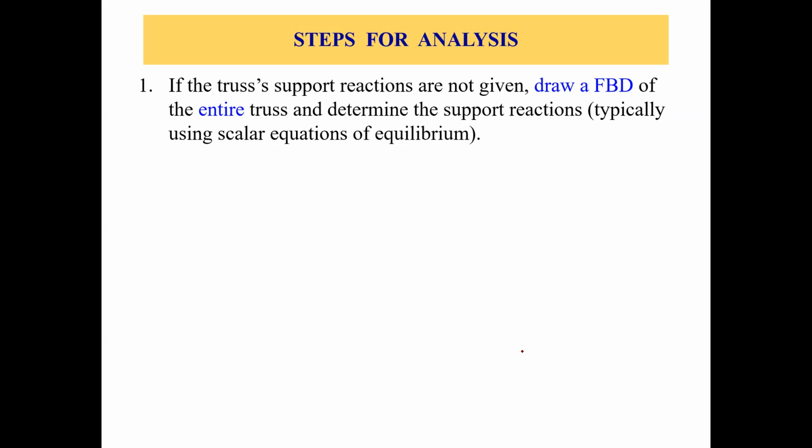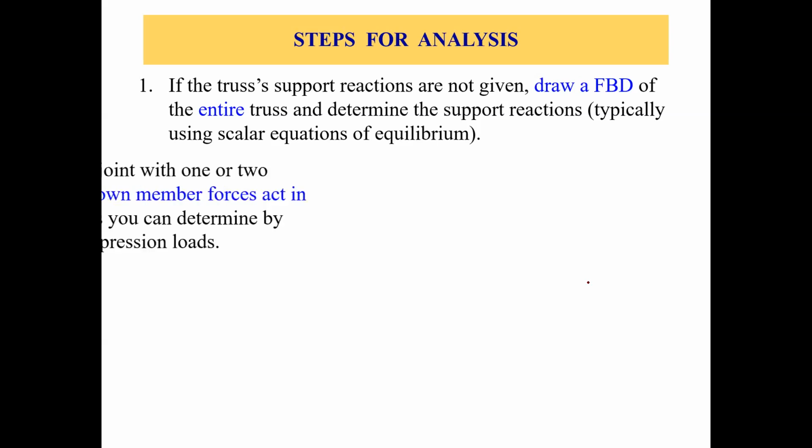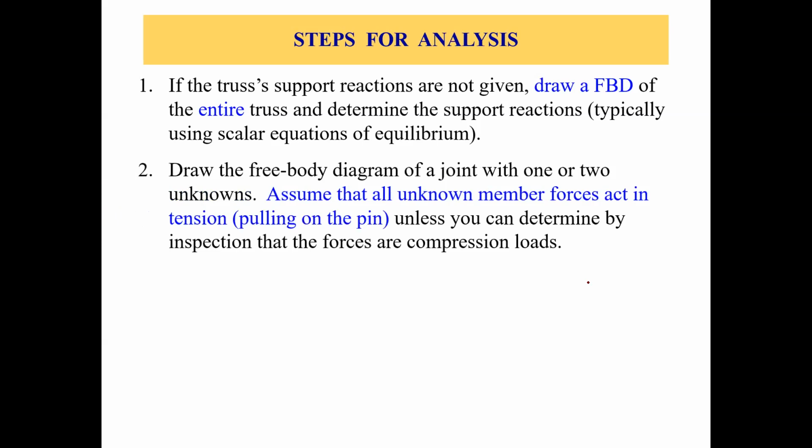So just make sure that you are using method of joints, but to find the support reactions, you need to draw a free body diagram of the entire truss, right? Okay, so with this step, your support reactions are done.